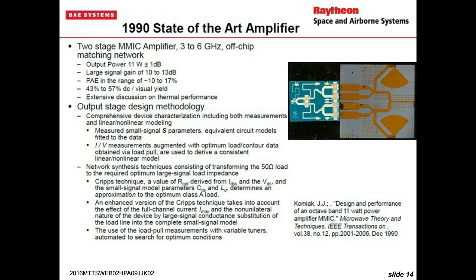So it makes it easier to do the circuit design and provide the proper wave shaping technique at the output to get to high efficiency. That said, there's a downside. The second device in cascodes, whether it's a common base in a bipolar or a common gate in a FET type device, is a good oscillator configuration. And so you have to pay real good attention to stability of the compound transistor.